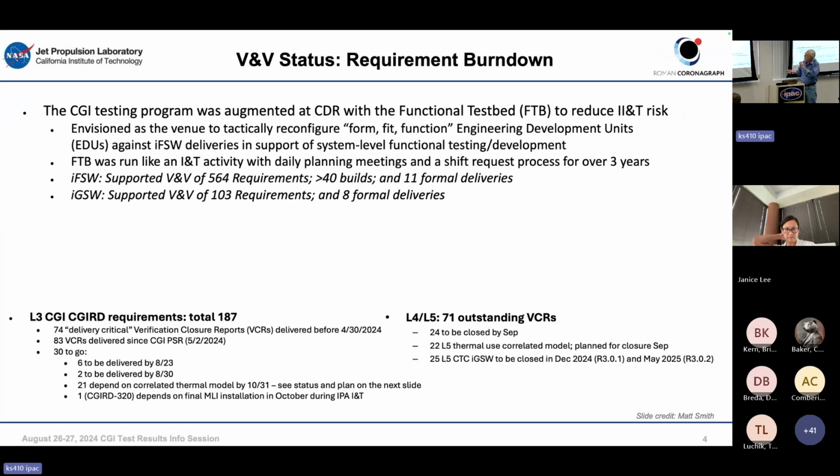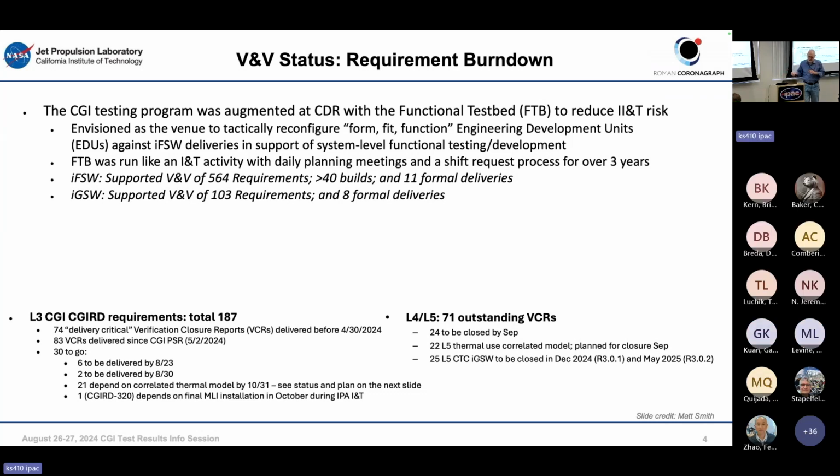It was built up out of the engineering development units that our electronics and avionics people built. This is the hardware to show that the form, fit, and function work, so they can characterize those units and develop the testing for the flight units that came later. Those units basically look like flight units, but you can't fly them. They don't have vacuum, temperature, or thermal compatibility, but they do function very much like flight hardware. And we actually had very good luck with that.